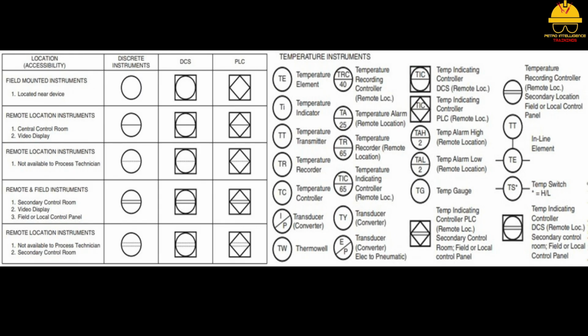Temperature is typically controlled with a temperature control loop, TIC. In this system, each of the 5 elements of the control loop will be temperature related and labeled appropriately. It is also possible to have other temperature symbols like temperature recorders, TR, high temperature alarms, HTA, and low temperature alarms, LTA.